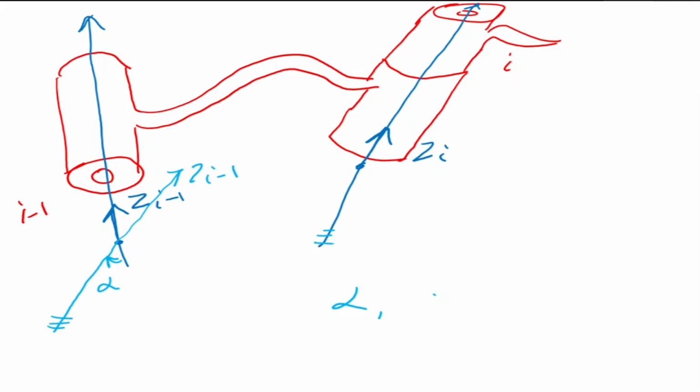So what I can do next is move along the shortest distance like this. This is the shortest distance, and this is my distance a. And now I put my x_i axis along this direction. This is my x_i-1 axis. I'm not drawing the y axis because as per the right hand rule, if you have z and x, y is automatically fixed.